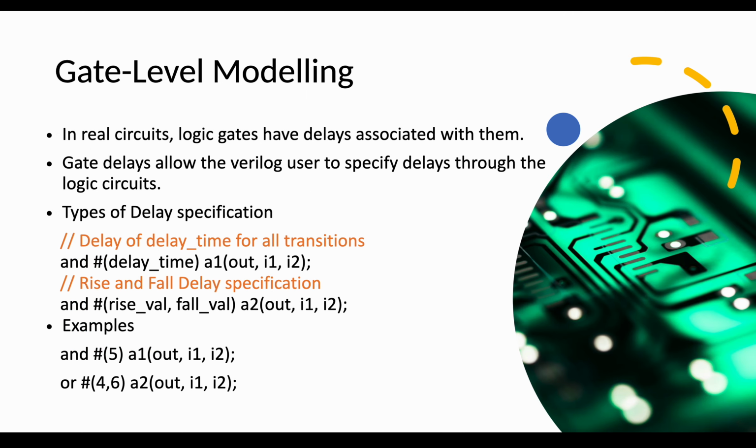So in real circuits, logic gates have delay associated with them. Gate delays allow the Verilog user to specify delays through the logic circuits. So the types of delay specifications: we have delay time, rise time, fall time. These delays are specified in a particular fashion that I have shown there.